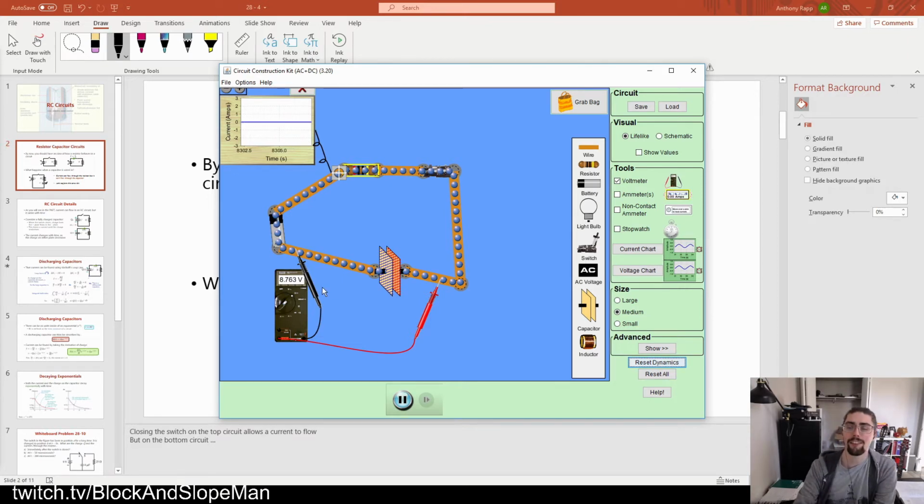What's happening here is that both of these factors are affecting what's going on with my circuit. In the case of resistance, that's stopping my current from moving there in the first place. So it's going to take longer to actually get to the capacitor, and it's going to kill the maximum current that I could see. By increasing the capacitance, the capacitor is at the start not trying to interrupt that flow of charge. As time goes on, though, as it gets to a higher and higher potential, there's less charge that can actually be moving around onto these things, and it's going to slowly decrease down. But those are the two factors that we see here that might be affecting things.